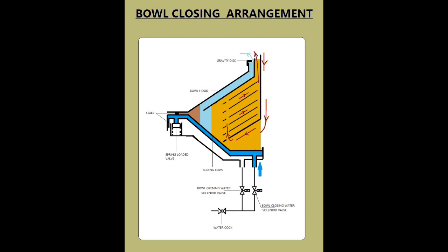The pressurized water chamber is sealed by spring-loaded plugs, therefore the seating surfaces must be smooth. If they are leaking, the ball will open and start to leak after some time. Some manufacturers give water pulses to overcome the losses of water in the closing water chamber, mostly due to minor leakages.